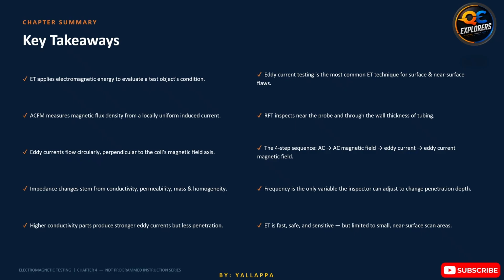In summary, eddy current testing is fast, safe, highly sensitive, and extremely effective for surface and near-surface inspections. However, its success depends on proper probe selection, correct instrument setup, careful calibration, and accurate signal interpretation. With these key principles in mind, let's test our understanding through a series of review questions.